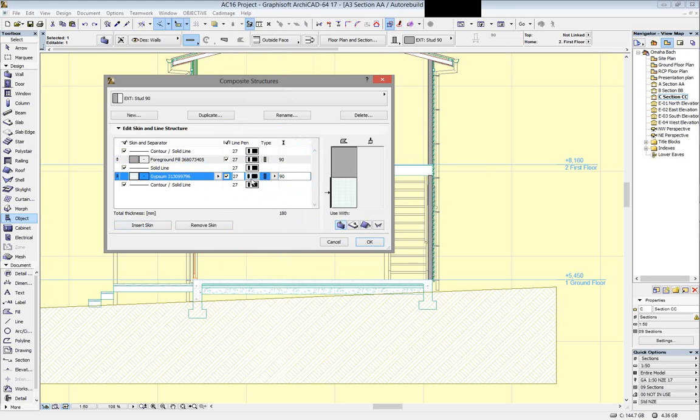As we move our way across the line here, we can come to our structure type. And this is not new, but core, finish, other. Now, a lot of little things going along here are making it more obvious for us to use composites in our standard process. One of the reasons I would use composites, and especially an internal plasterboard, is if I wanted to show my plasterboard in my 1 to 20 bathrooms and kitchens, and I wanted to dimension to my plasterboard so that I made sure that my bath fitted and my shower fitted and my kitchen fitted,